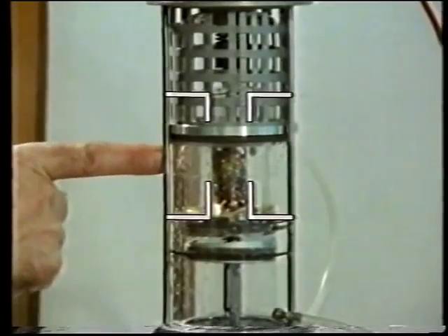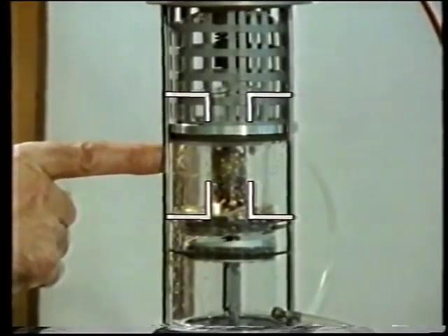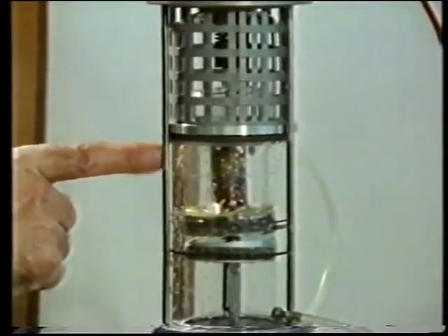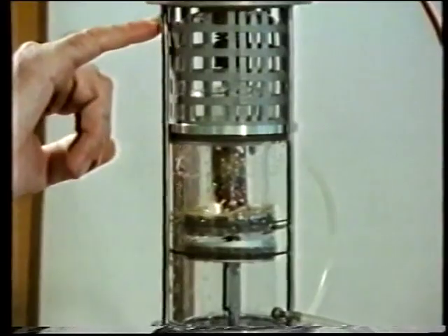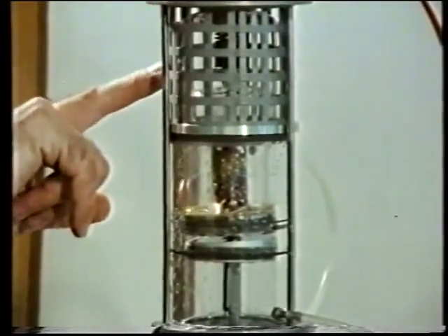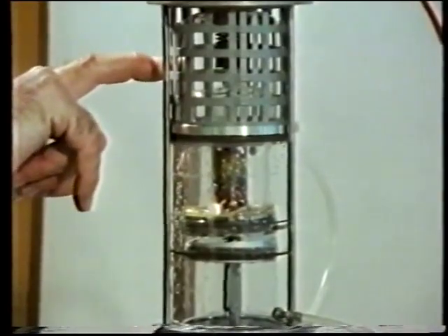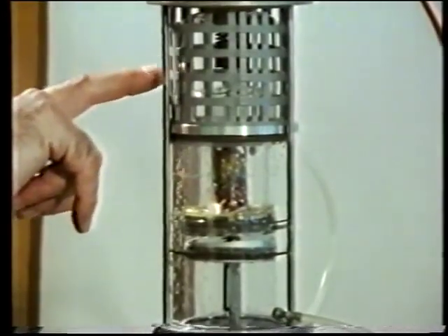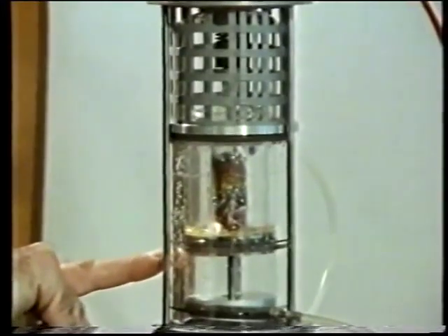The passageway has porous copper which acts as a heat store, which is called a regenerator. With the power piston and the displacer in their top position, the gas is contained wholly within the hot space. The gas is at high temperature and high pressure. The high pressure gas forces the piston downwards, which produces a power stroke.